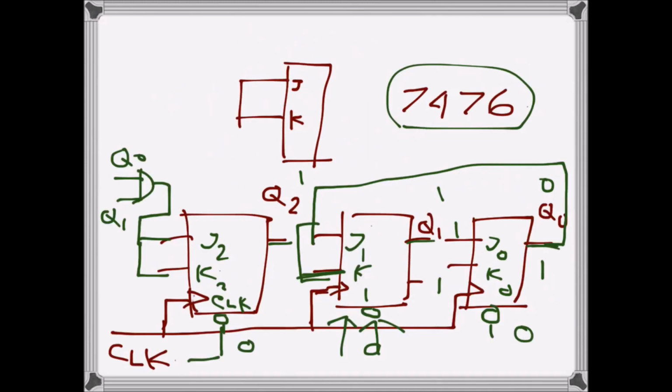We should connect it here, I don't have enough space here, that's the problem. So basically what I'm trying to do here is a NAND gate here, and I won't draw the connection, so I will just label them here Q2 and Q1, and these two will be connected to the NAND gate. This output will be connected to all of the clears, all three.